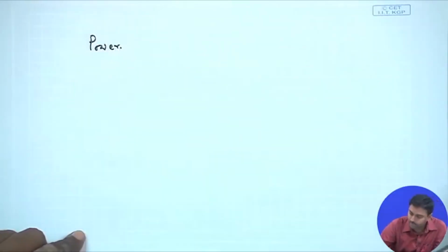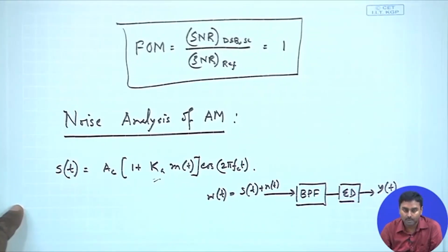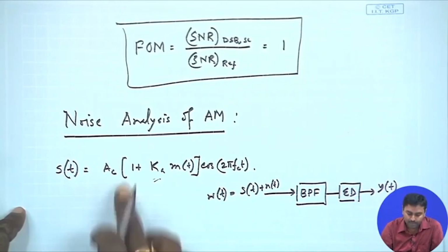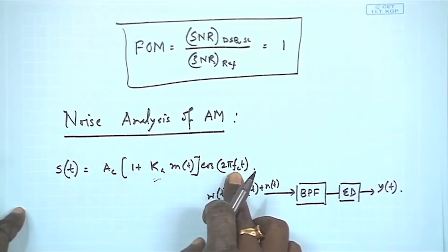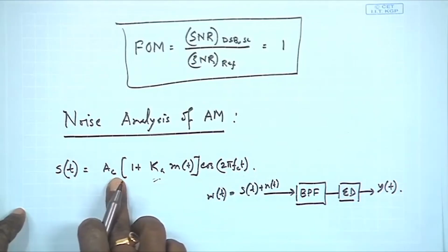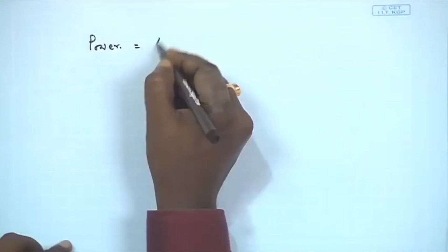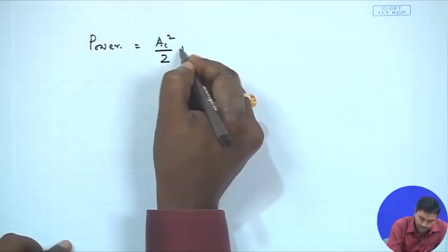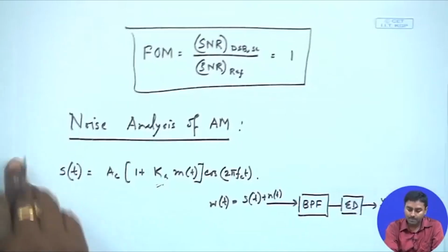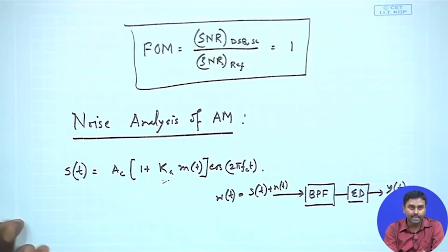So, what is the power that is launched whenever we do this modulation? Okay. So, the power that will be launched, see this Ac cos omega_c t, that is a cosinusoidal signal with amplitude Ac. We know that the power of that is Ac square by 2, right. This is something we have already done. So, that must be Ac square divided by 2 plus this Ac into Ka, that is already there, right.